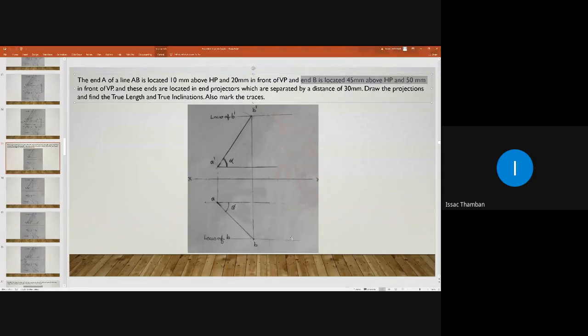Similarly, you will draw another horizontal line through point small b like this, and that is the locus of small b. You draw the locus lines. It must be thin lines. Have you drawn the locus planes? Yes, sir. Okay.